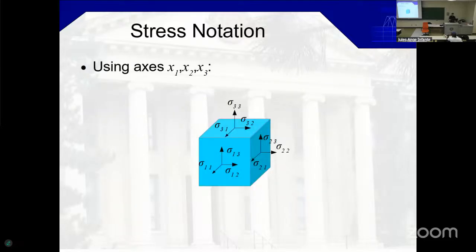Maybe this will give you an idea why we call them Y. See, if I call them X, I need two indices for my stress, and my stress, I just call it sigma. So the normal stress in this plane, in plane X1, becomes sigma 1, 1. Because it's normal, it's on plane 1, so it's normal to 1. And because the second index is the same as the first one, it means that it's the normal stress.